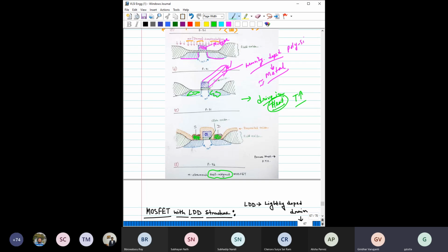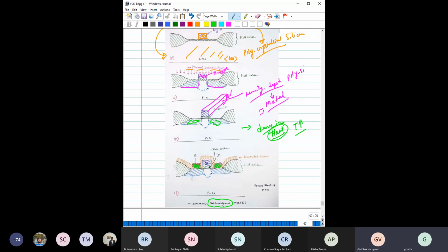However, you should also know that in modern transistors, polysilicon cannot be used any further. So again, we have come back to the metal gate in modern transistors. So we started with the metal gate, in between we used polysilicon as the gate, and then again for modern technology we are using the metal gate. So it is metal, poly, metal in terms of timeline. Okay, I hope this part is clear to you. Self-aligned process, what is the advantage compared to the gate-last process?